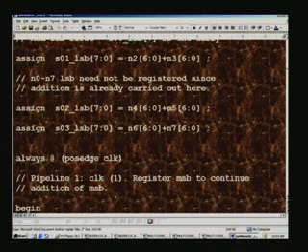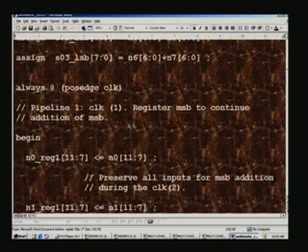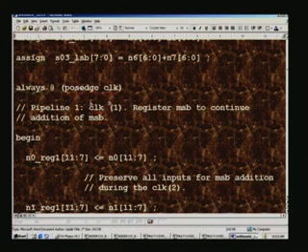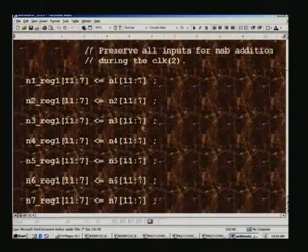We add just the LSB, and we latch or rather register when the first clock arrives at the positive edge, and this is pipeline 1 and clock 1, register the MSB to continue addition of the MSB. Since we are not adding the MSB, we had to register it separately, that is what we are doing here. This is the MSB for all the numbers, and then propagate it for use when the next clock arrives.